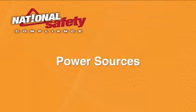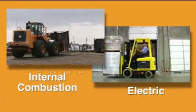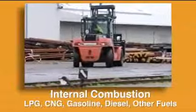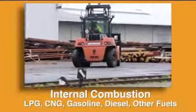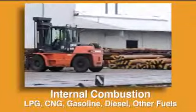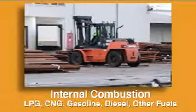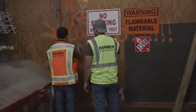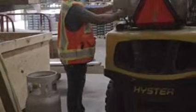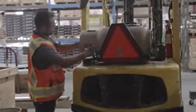Power sources. Currently, there are two main power sources for powered industrial trucks: internal combustion and electric. Internal combustion runs on liquid petroleum gas, LPG, compressed natural gas, CNG, gasoline, diesel, or other fuels. Refueling can be dangerous. Make sure you refuel only at designated safe locations and always turn off the engine before refueling. Never smoke while refueling, and follow all safety instructions of the manufacturer and your employer.